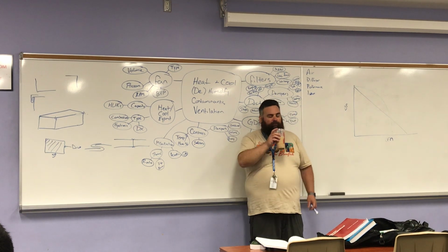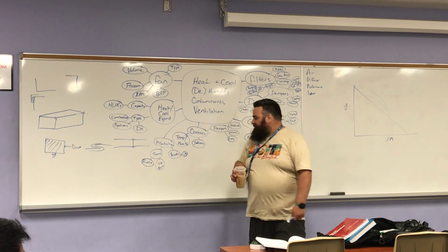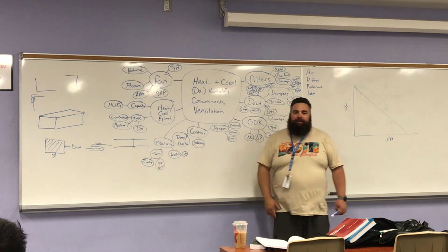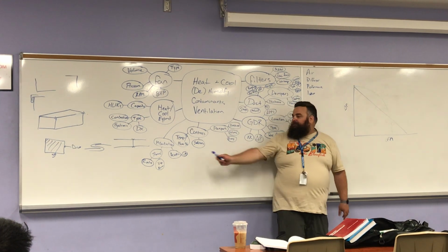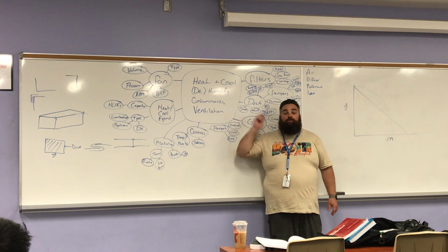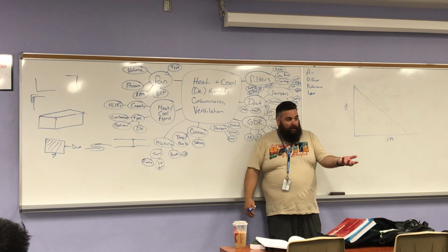Doesn't it also make the duct size smaller on the inside? Reduces the... I don't know. Very good. That goes back to my delta P. That affects my delta P, my pressure drop, in two ways. The first is we've changed the roughness of the duct. There's a lot more friction now. The other way is we've changed the free area of the duct.